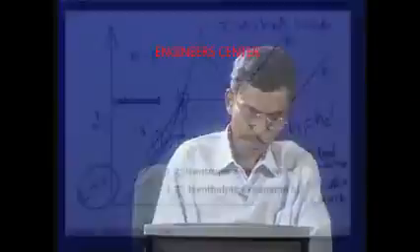So when some liquid flashes into vapor in an adiabatic device like a turbine or a throttling device, the temperature of the rest of the fluid has to reduce, because it has to supply the energy required for the vaporization. As a result, the temperature of the entire system reduces. Here the system means the fluid which is undergoing the expansion. So you must keep this in mind. The significant drop in temperature is taking place because during the expansion process vapor is being generated, and the energy required for vapor generation is supplied by the liquid itself. As a result, its temperature drops, right. So this is the principle.